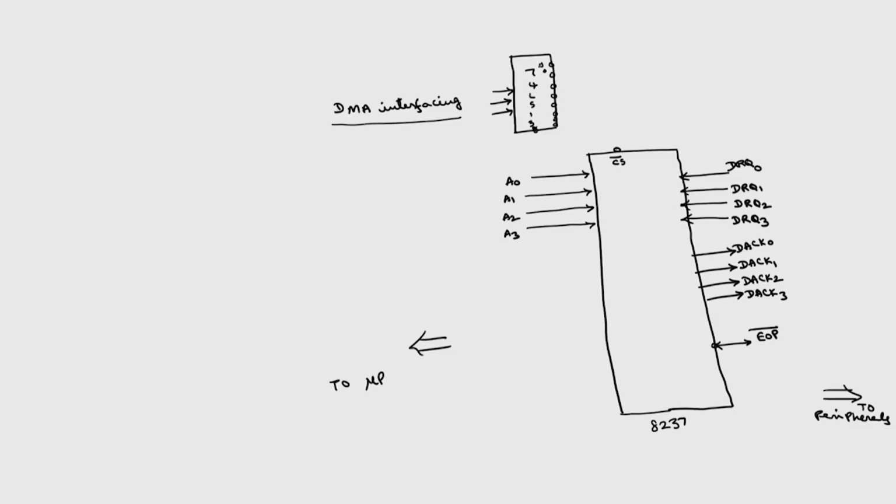This is O0, this is output 0 signal. So, this I will connect to chip select signal. Accordingly, you will get some addresses. If you want, you can connect O1, O2 also, O7 also. This will be having total O7. So, this is A0, A1, A2. Then we have 2 active low signals E0, E1, and E2 there is active high signal. These are the different signals for a 3 to 8 decoder 74LS138.